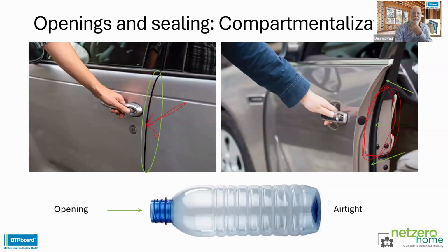So here's the weather stripping on the door. And the reason that that's inboard is because the amount of liquid that would hit the surface on the outside is significantly higher than the amount that would hit the weather stripping on the inside. So if we could simply look at our opening in our window and say, okay, here's the outside where this opening is, here's the flange or the exterior component of the window.